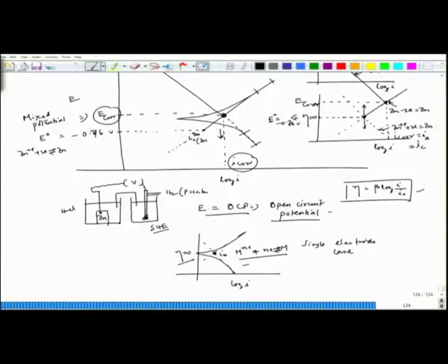In this case we have to consider I_C minus I_A, and this is for hydrogen and this is for zinc, and in this case also we have to consider the difference I_A minus I_C, and this is for zinc and this is for hydrogen. So, that is how we get these Tafel plots, and accordingly we can extend these two linear portions backward and achieve this particular point, which is nothing but I corr and E corr. This is one important piece of information we get by doing Tafel experimentation.